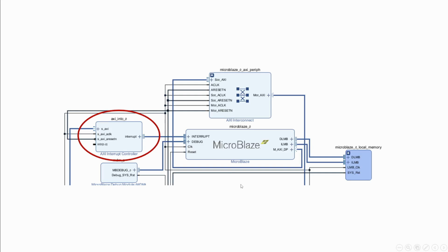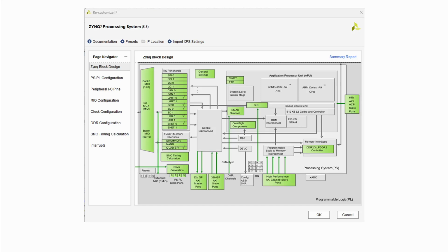We will work also on the Zynq. Now the Zynq is a SoC. It's a system on a chip. It has a CPU, but it has other peripherals inside the SoC. Among them, we have the GIC, which is the general interrupt controller, which connects to the interrupt, and we will use outputs such as the UARTs.